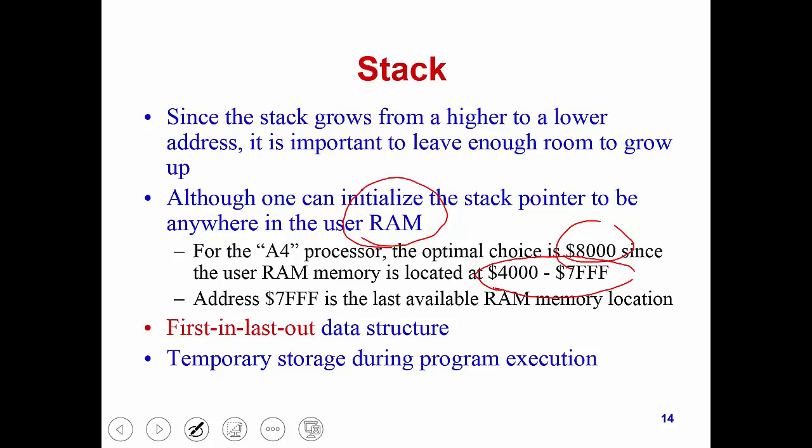So we simply call 7FFF the last available RAM memory location, or the first memory location that you can store data, but it has the highest address. Different microcomputer systems have different specifications for the range of RAM. But for the A4, which we commonly use, it starts from 400 to 7FFF. In this case, it's better that we initialize the stack pointer address to 800.